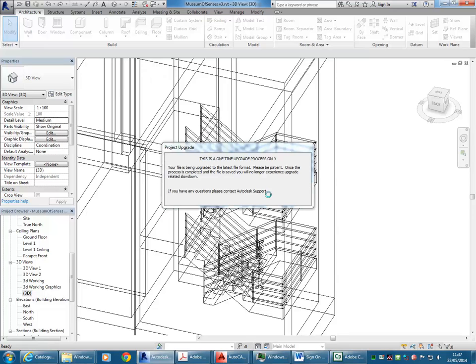you'll see all these pre-made railings. People often think there aren't railings and stairs in the library because you don't have a railings or a stairs folder. It's just because you load them in differently. They're there. And walls and floors and roofs as well.